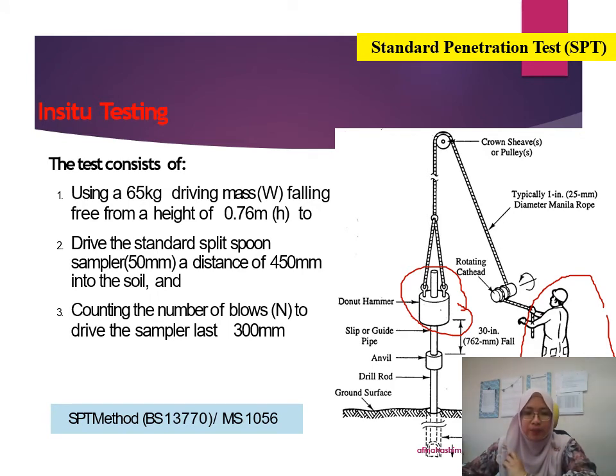And then we can also remove the cone of the standard penetration and replace it with the sampler, and then we can take the soil sample from the testing.